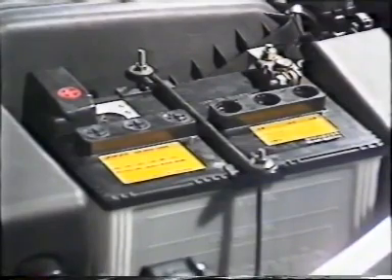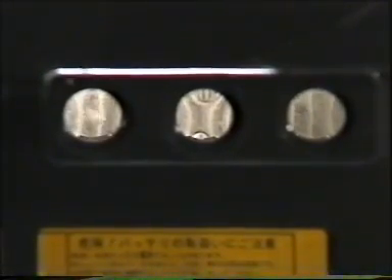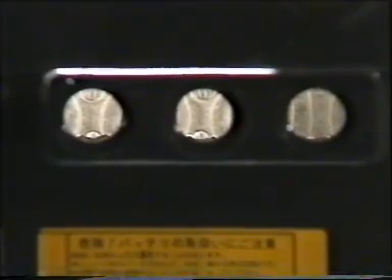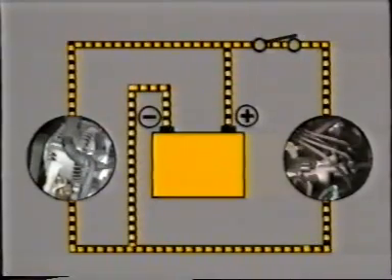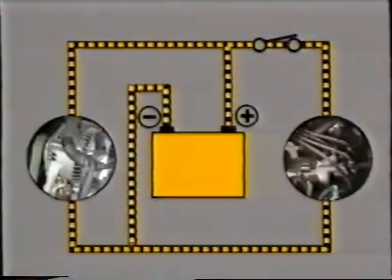Another typical fault is overcharging of the battery. If the battery is overcharged, a lot of bubbles will be seen in the electrolyte, the electrolyte will decrease considerably, and the light bulbs and fuses will not last long. This is probably caused by overvoltage from the alternator.